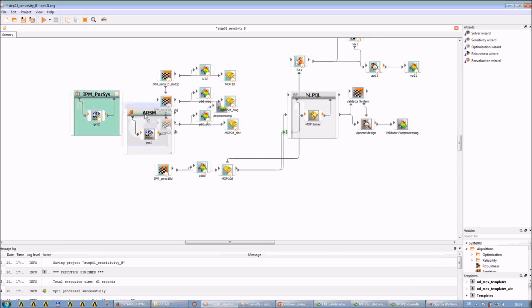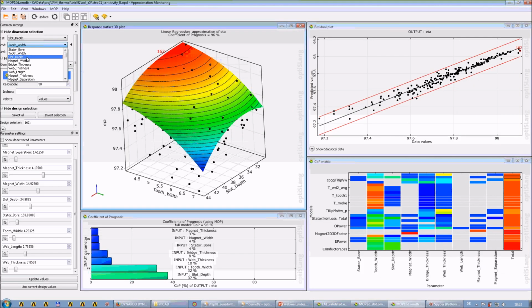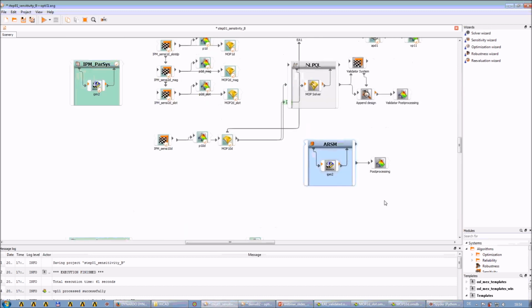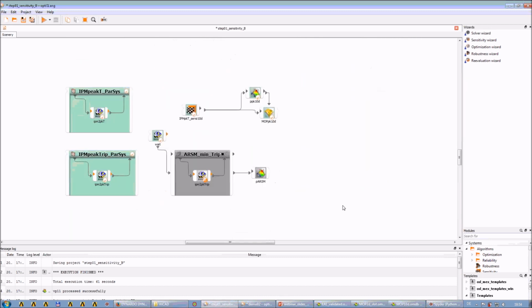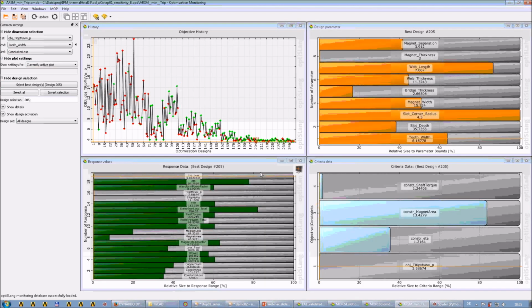So by contrast, this optimizer runs calling Motor-CAD. And I conducted an optimization. I just stopped it this morning. And this optimization was the working point at high torque, high current. And it had the goal to minimize the torque ripples. So let's look at the torque curves.